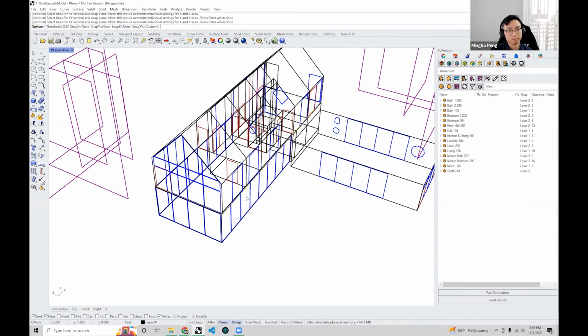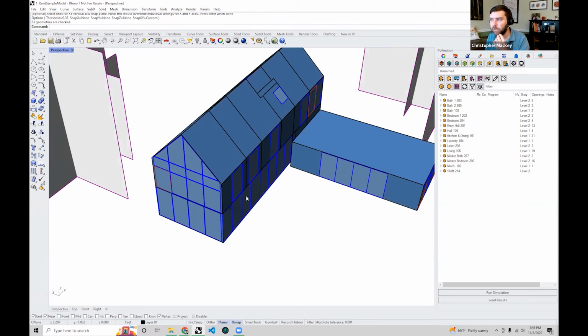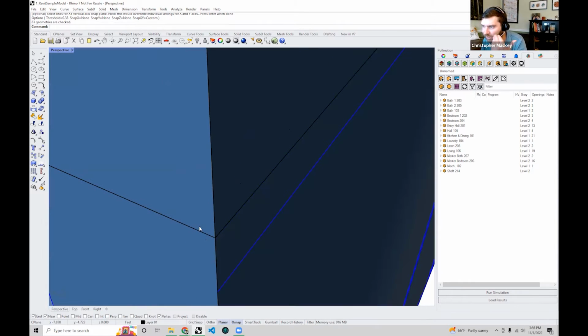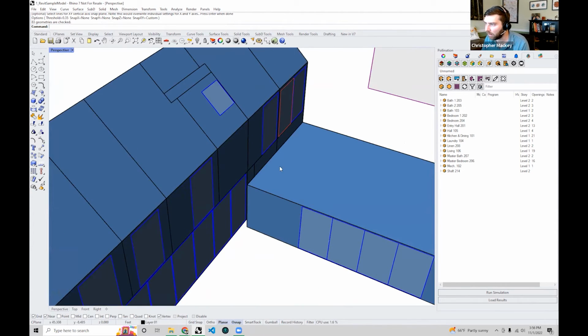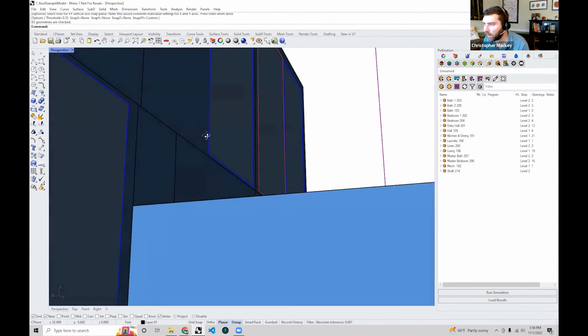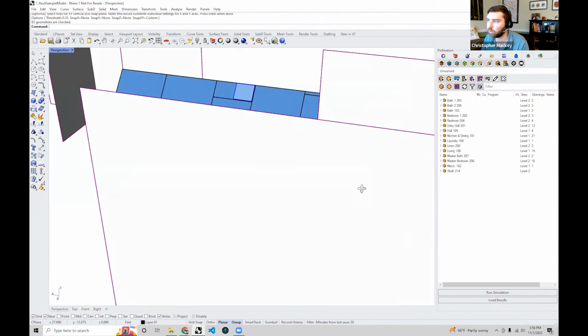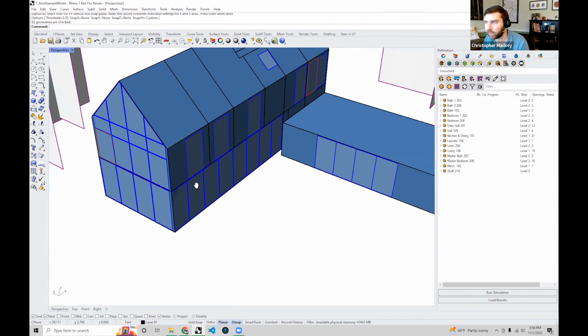Oh, I have to hit enter one more time, I guess, in case I want to change the threshold again. But in this case, now when I hit enter, it should run. And 83 geometries were checked, and look at that. That's all nicely aligned together here. With these two curves, it aligned all the rooms together. And this looks like it's in really good shape now, much cleaner than what I started with, all those coplanar faces merged and everything aligned to that grid.